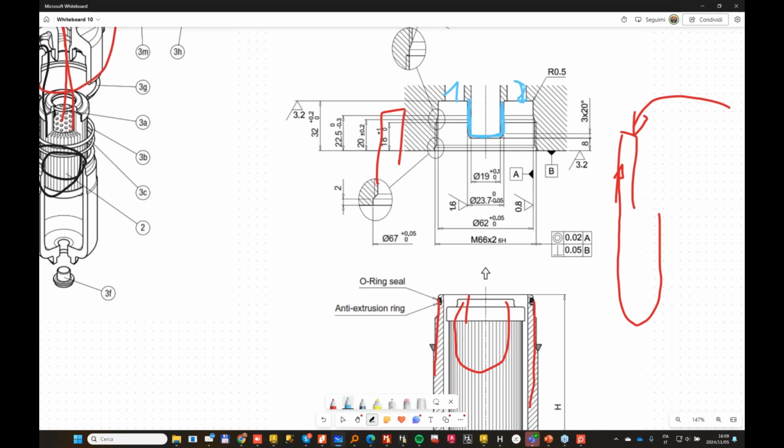Of course, it's always better to give symmetry. This will not be our case for today, but if you have inlet on one side, it is better to try to symmetrize the inlet flow so that the cartridge of the filter will work better. But in terms of design, sometimes it's more the geometry that is driving us and constraining where we enter.